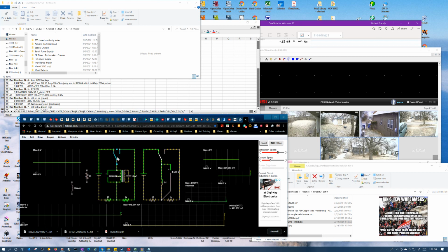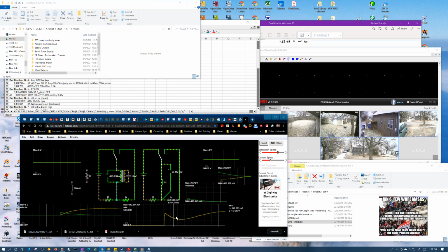But at any rate, if I charge both of these up, you can see your curve here, and these are 5 volt supplies, by the way. So it starts at 5 volts, and you can see the voltage drop across it as the field starts to charge up. Now, what's interesting is to note the difference between this charge curve and this charge curve, because remember, inductance-wise, these are the same. They have the same resistors. But because I've got a pretty big capacitor in this, a 10 millifarad capacitor, it has this rather unusual charge curve.